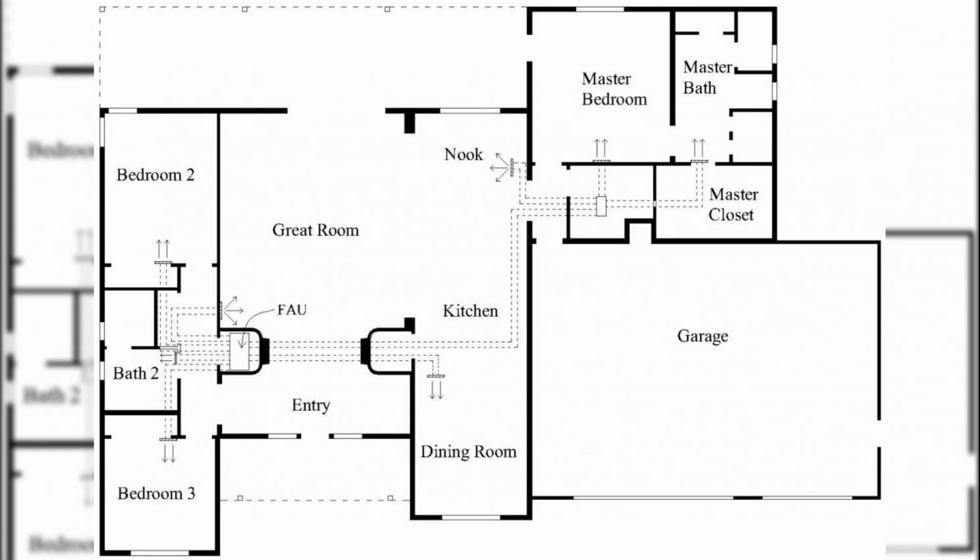Register selection also matters a lot more than people think. The experts showed that high sidewall supply registers on interior walls work well for both heating and cooling climates. Throw distance is more important than spread for effective air distribution in high-performance homes. Higher air velocity, 800 to 900 feet per minute, provides much better room mixing than traditional velocities, 400 feet per minute.